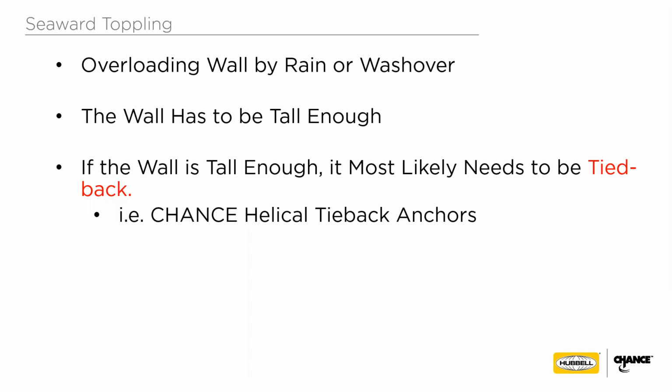All right, so seaward toppling, overloading the wall by rain or washover. So you want to have your wall be tall enough to minimize the chances of that happening. And if your wall is tall enough, it most likely needs to be tied back because you won't be able to cantilever a height that tall. So that's where the helical tieback anchors are a great solution.